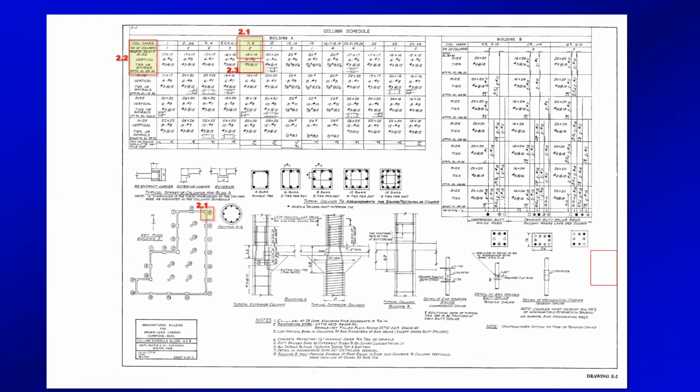And how does that differ from the other ones you're saying? All right, so look at this column. To answer Ed's question, look here for the square columns or the rectangular columns. You see rebar. There's your tie coming across, and these are at 12 inches on center. So from there to there to there is 12 inches. On the spiral columns, they're still number 3, so they're 3/8. They're wrapping around and spiraling up this column. From this distance to this distance, if you can see what my mouse is doing, that's 2¼ inches. That's the difference between the two.